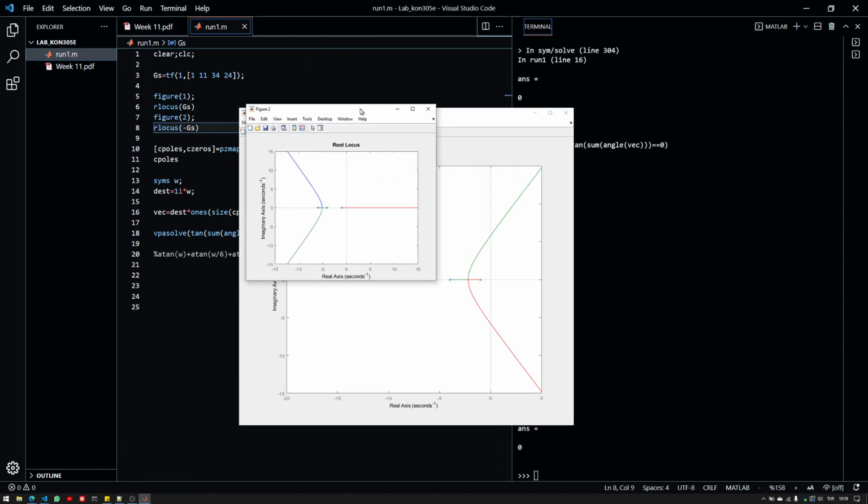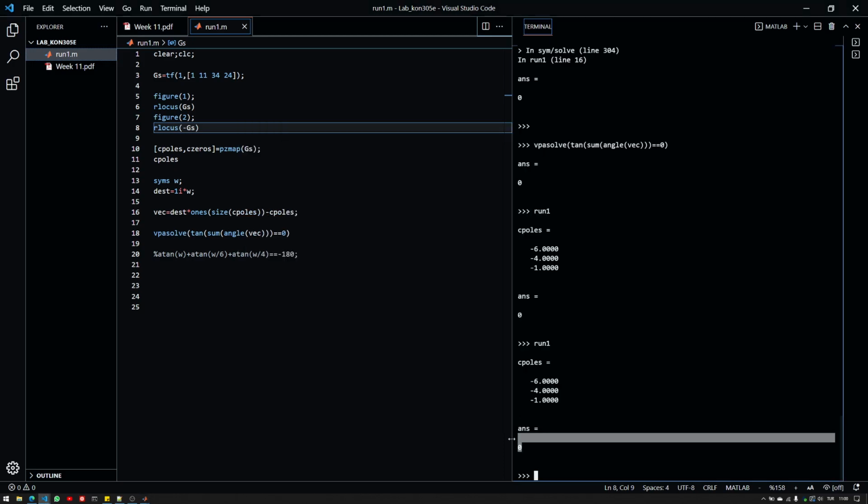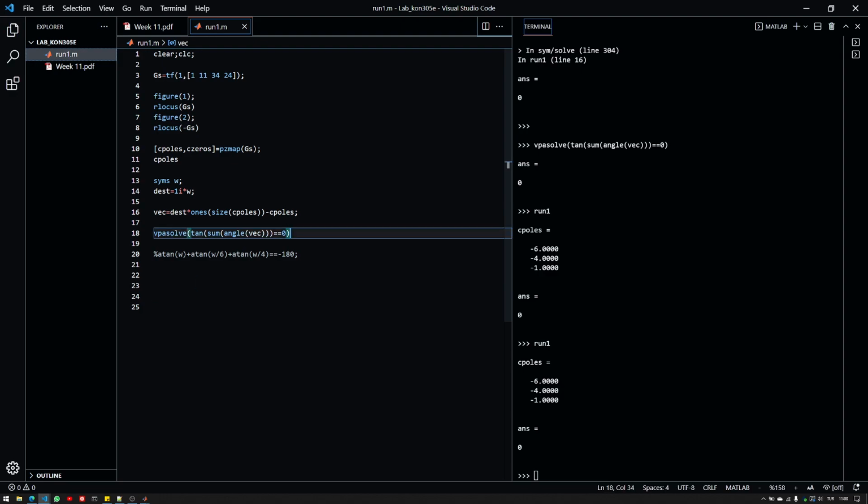So you can see there is an omega value equals 0. If you look close, you can see that this is the origin. And if omega is 0, this means that there would be one crossing where omega is 0. So the real part was originally defined 0. So if omega is 0, then you have the origin. So we kind of found one solution to this equation, because there's no rule that indicates that this point should be only on the j omega axis. It might be also the origin itself.